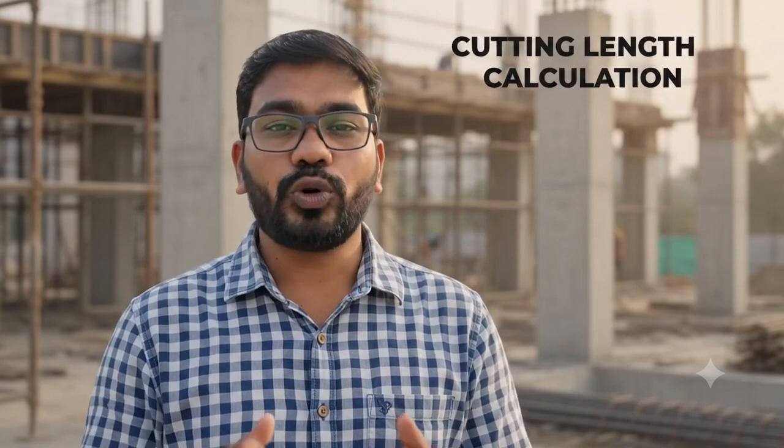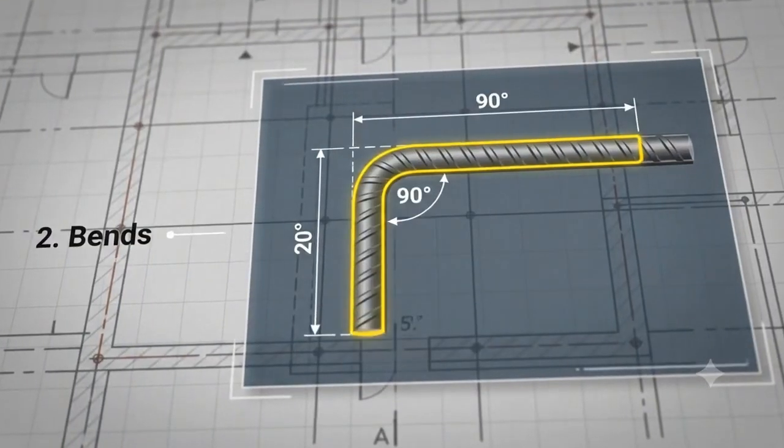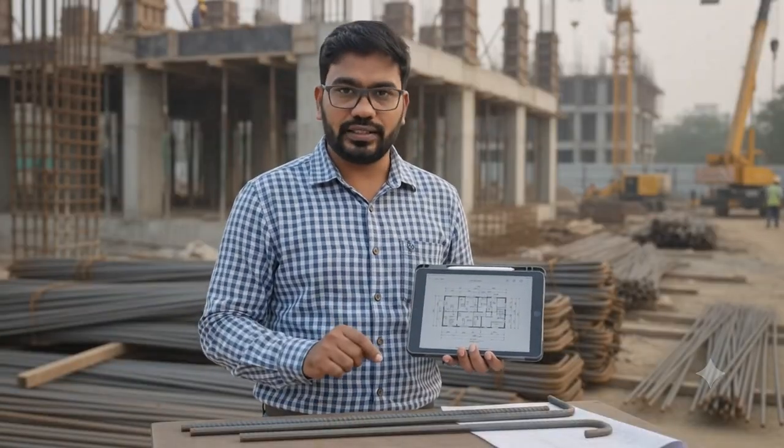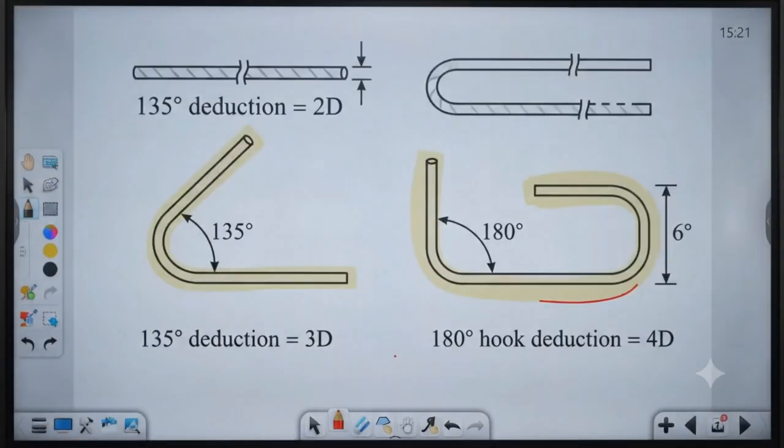Now let us learn how to calculate cutting length. The cutting length depends on straight portions, bends, hooks and development lengths. For a straight bar, cutting length equals actual length. For bars with bends, additional lengths are added or deducted. Typical deductions include several angles. We have the 45° and 90° deductions, also the 135° and 180° hook deductions. These are essential for accurate steel cutting.